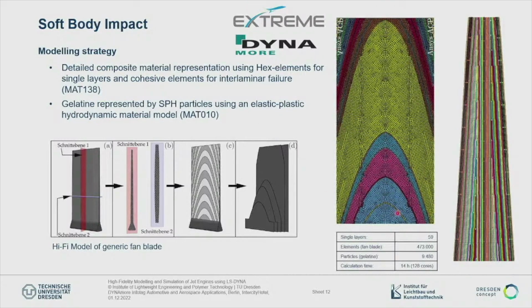Just exemplarily, the geometry of the single plies is complexly stacked. You have the root section, which has its own stacking sequence. And what we did here, we used quite a high resolution to model each ply separately to capture the failure behavior. This refers to the high fidelity aspect of capturing the actual material structure.